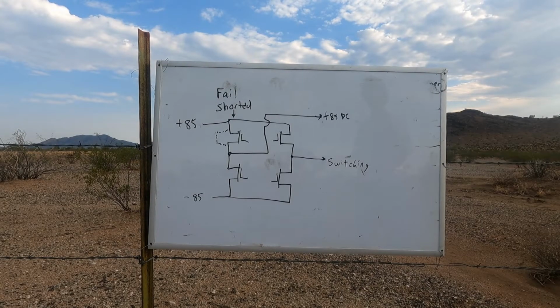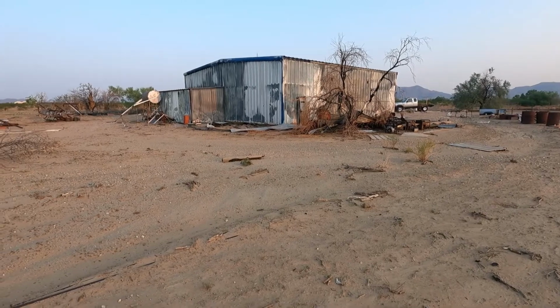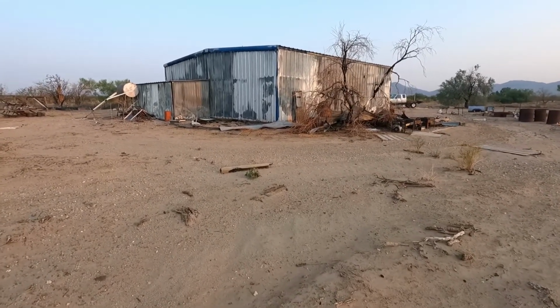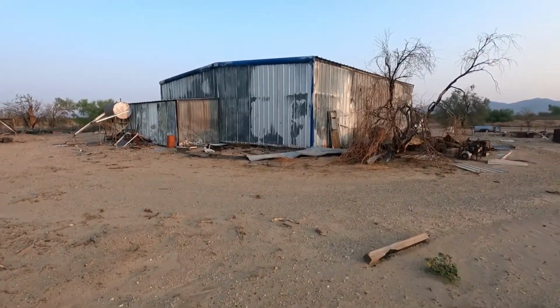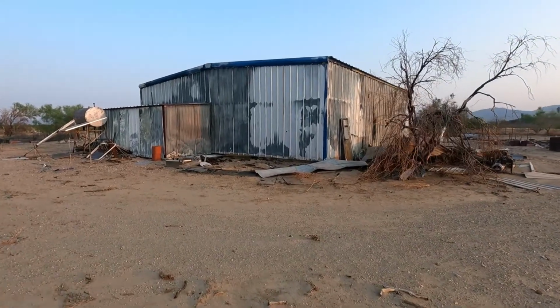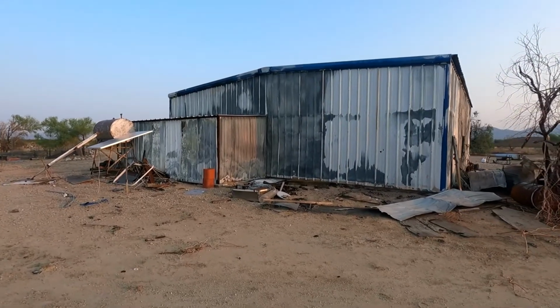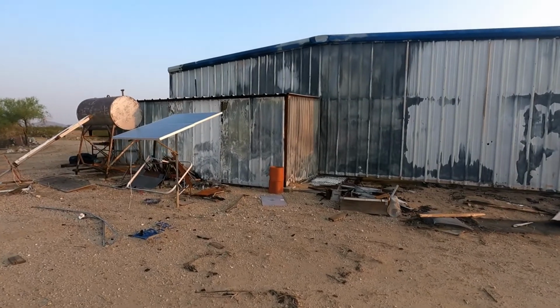But wait, silly me. Everybody knows that semiconductors don't fail. Output switches don't fail, especially shorted. If I was an inverter manufacturer, I'd give a lot of thought to the consequences that may occur due to the failure of just a single transistor in somebody's solar power system.